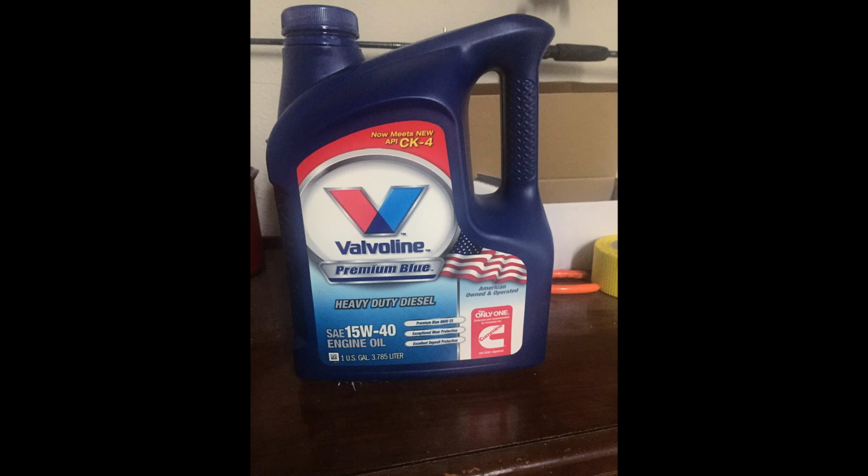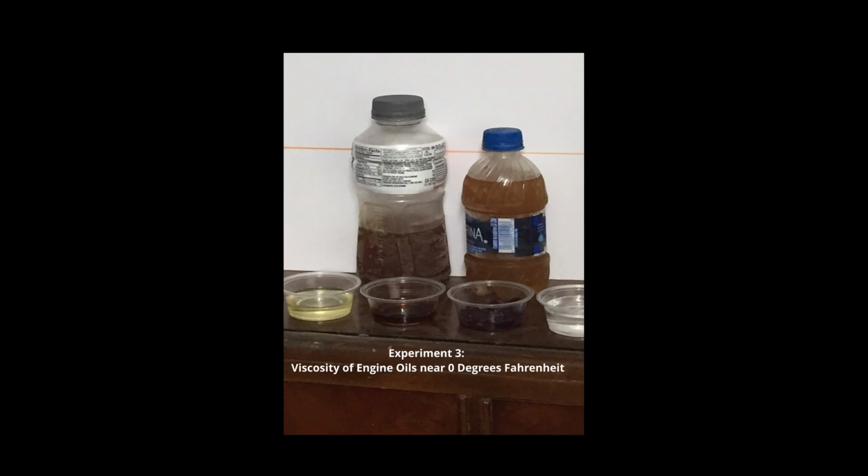The 10W-30 oil would be ideal for a relatively hot summer and not so cold winter, much like the climate in the southern states. Oil thickening is sometimes bad for certain vehicle engines that have smaller spaces between the mechanical parts for the engine oil to move through. It can also put a strain on the oil pump. If the oil is too thin, it does not provide the required oil film thickness to separate metal surfaces, especially in the valve train. And when this happens, metal surfaces will eventually wear out and eventually destroy the engine.